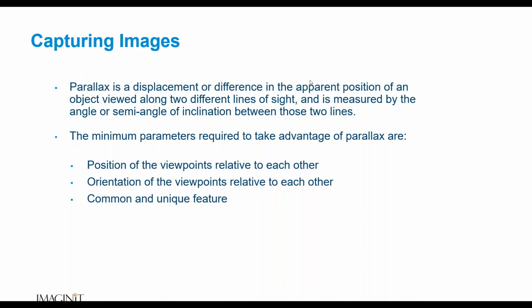So if we were going out and taking measurements and creating a point cloud with a terrestrial-based laser scanner, there are some things that laser scanners are going to do a little bit better than photogrammetry. If I've got a big blank wall, it doesn't matter that I have no unique features on it. I can still use a laser scanner and scan that wall and get that point cloud relatively easily. You've got to be a little more cognizant of that big blank wall when we're working with photos.